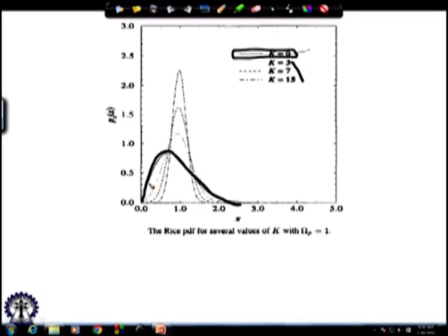However, for non-zero values of the Rician coefficient, the distribution slowly becomes narrower and narrower as the coefficient increases, and it peaks. So, when k tends to infinity, it becomes very narrow, almost concentrated in one place, with very high peaks, which would mean that there is hardly any variation of the signal, which is denoted by x.